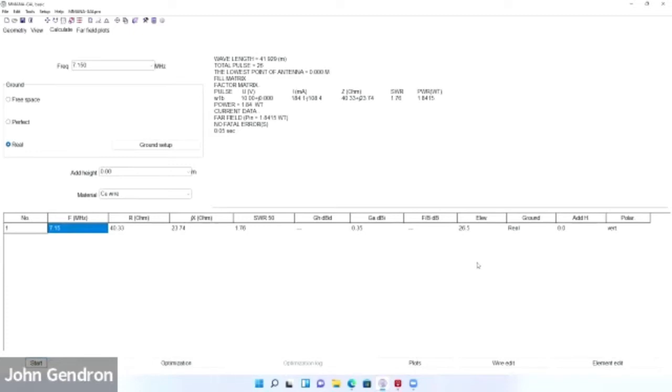Okay, but for purposes for us, if we wanted to operate this antenna on 7.15, guess what? It'll be fine because it's below 2 at that point in time. Okay, our radios are going to be fine with it. It's not even 2 SWR, so your radio's going to be fine. How efficient it's going to be is a little different.